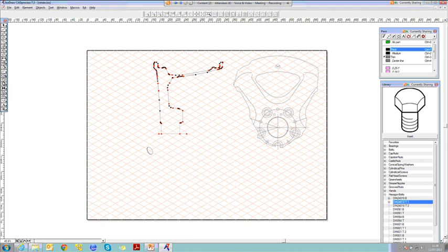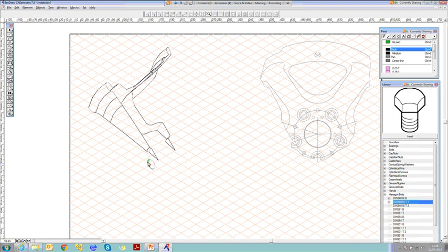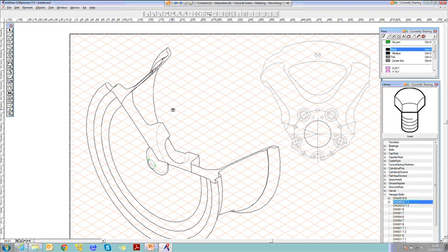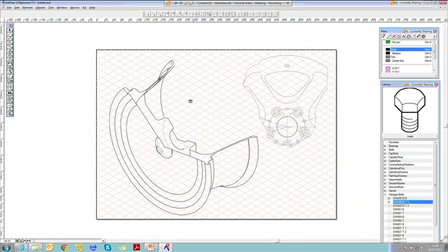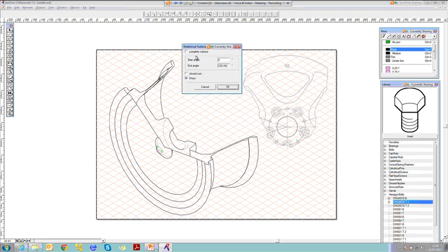And we also have a revolve tool. If I click on my revolve tool from my little toolbar, and these toolbars you can move around, you can position them in the window wherever you like, I then get a little hand on my mouse. So I'm going to take my hand and drag this and drop it onto my circle. When I drop it onto my circle, IsoDraw realizes that I want to revolve this shape. I then get my little drag handles to be able to revolve that round to a specified angle that I choose. So again, when I'm finished positioning this roughly where I want, I can finish off my projection or my revolve.